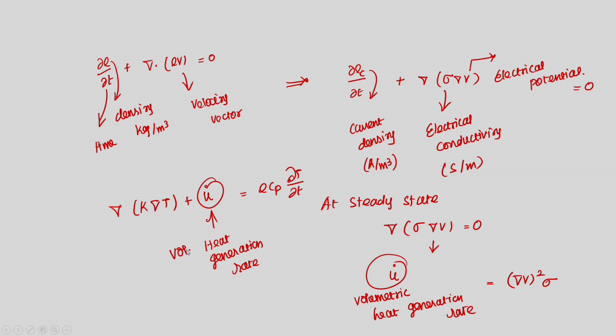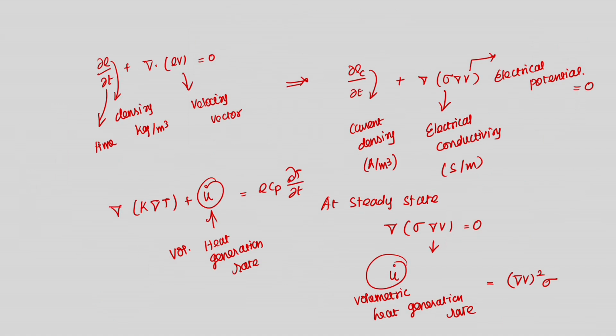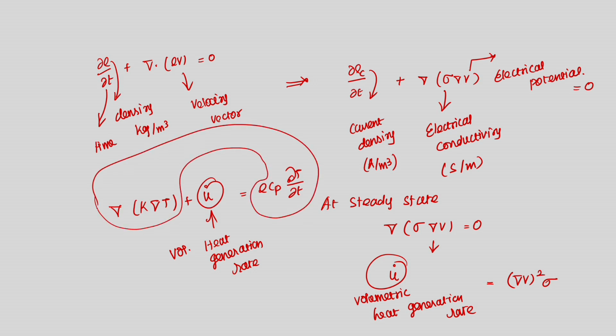To get to know this for liquid food, we are supposed to get the localized velocity. This will give me how the temperature is, because in a convection system your temperature alters your velocity and velocity alters your temperature. This gives me the localized velocity, from which I can model the system better. Normal thermal processing will have only these components, but here you have a volumetric heat generation, which can be related to the ohmic heating principle using this equation.